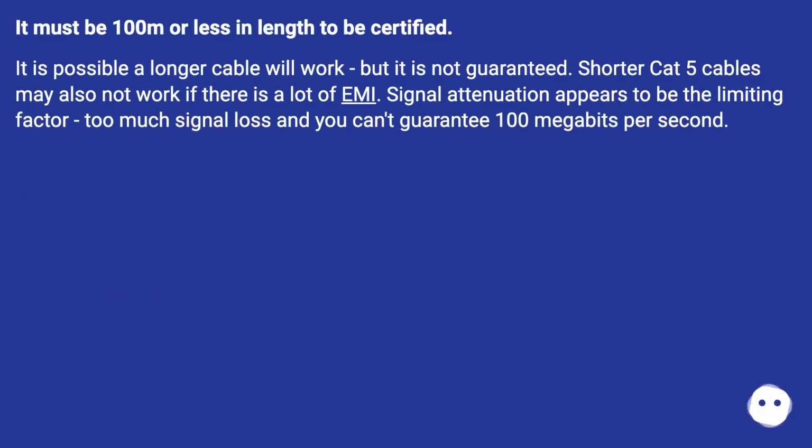It must be 100 m or less in length to be certified. It is possible a longer cable will work, but it is not guaranteed. Shorter CAT5 cables may also not work if there is a lot of EMI. Signal attenuation appears to be the limiting factor: too much signal loss, and you can't guarantee 100 megabits per second.